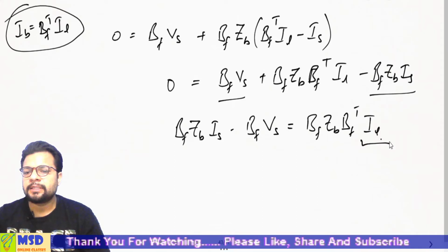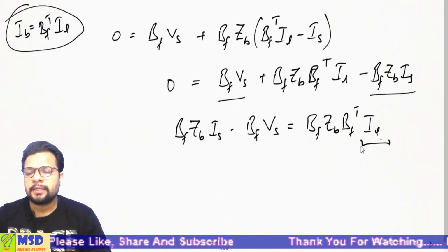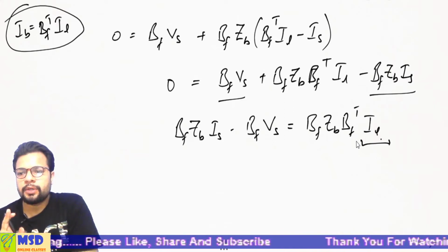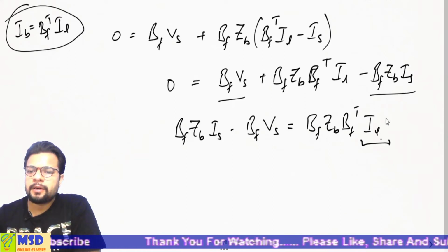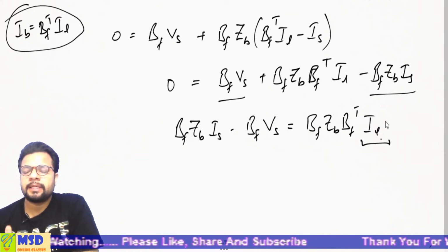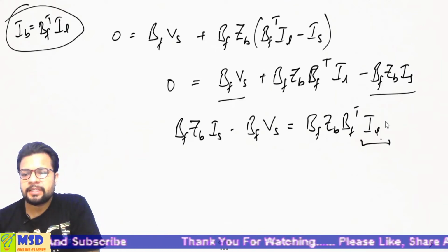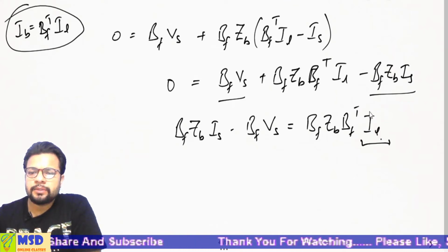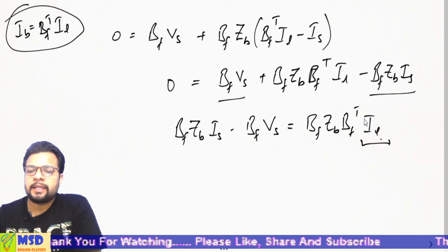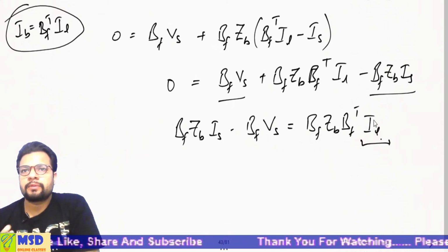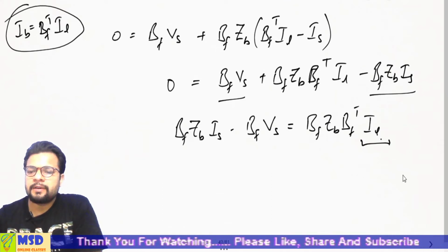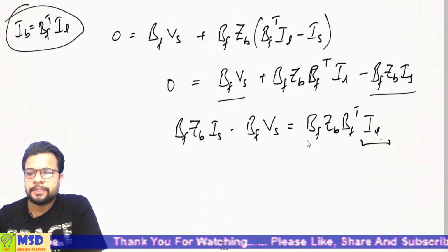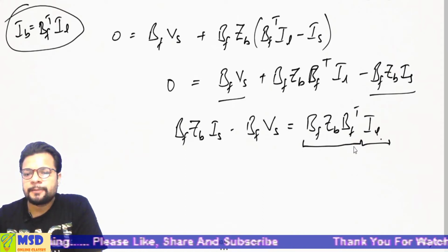Now see, this is your link current vector, या जितने भी loop current vector कह सकते हैं। For every link connected to your graph you form a fundamental loop. और fundamental loop क्या होता है, इसके लिए previous जो हमारे sessions हैं उनमें आप देख सकते हो। वहां पे मैंने define किया हुआ है कि what is your fundamental loop. तो ये जो loop current vector है ये क्या ले रहा है, if you are having 2 or 3 loops, then it is a column vector with IL1, IL2 and so on loop currents. Now it is multiplied with this.